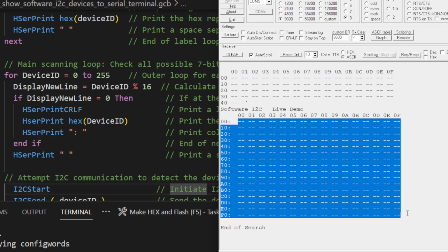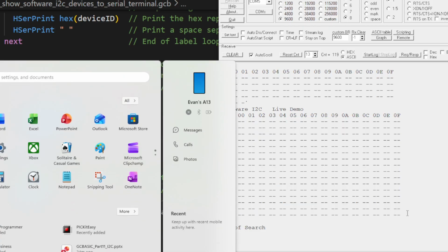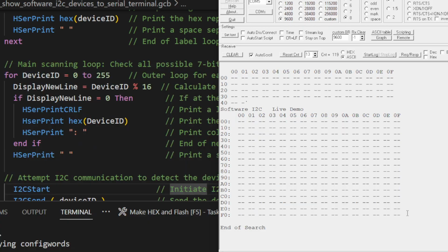That is because the PPS is still set. The registers have not been reset by the programming cycle. So what you should do, if you really want to be perfect, is always turn off the PPS by setting everything to 0. But there is a quicker way.